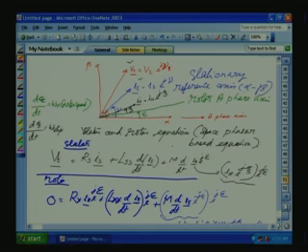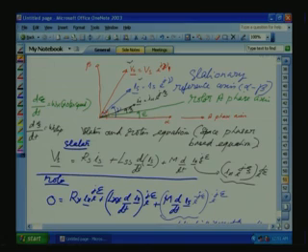there can be a voltage induced at the stator due to the mutual inductance. Why mutual inductance? All the flux due to IR will not couple to the stator. There is a mutual plus leakage part. So, due to the mutual only, there is a link between the stator and the rotor. So if you see here, M into d by dt of IR underscore is the current defined with respect to the rotor axis.